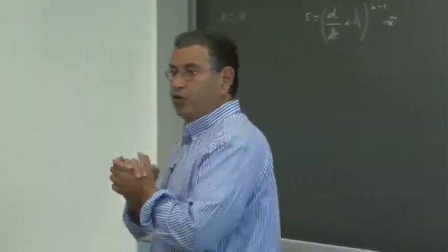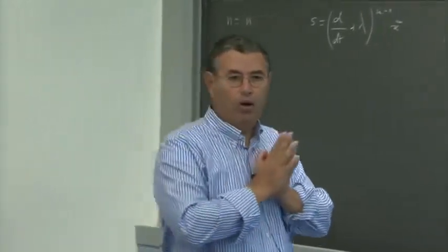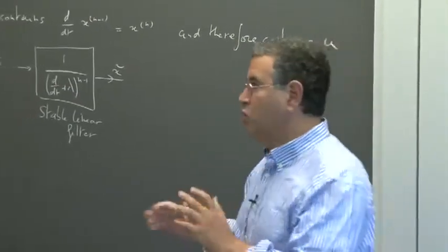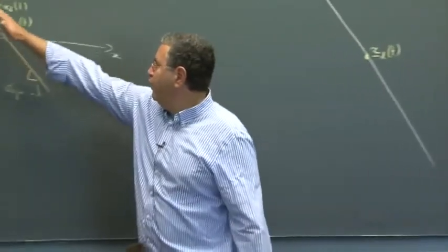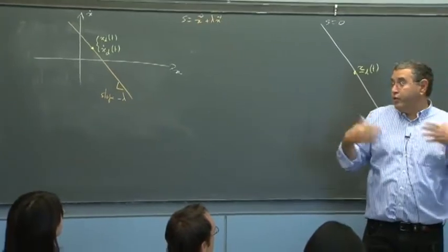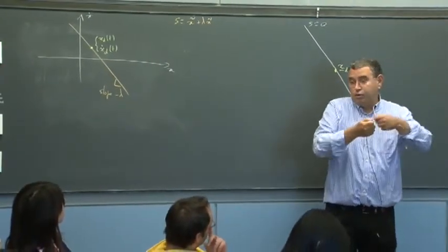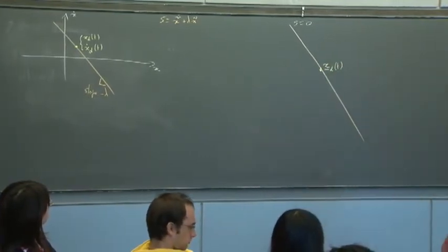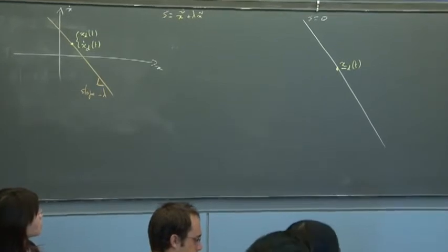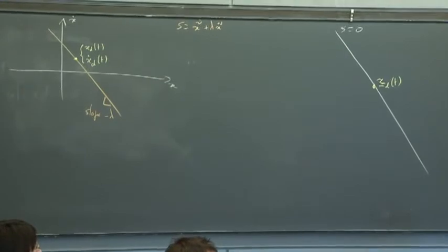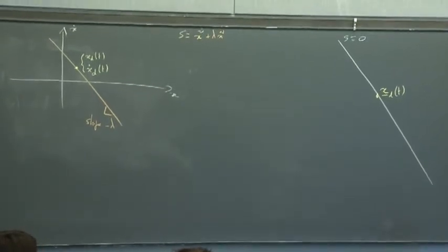Now, suppose that somehow you've made S tend to 0 and stay there. In other words, you've constructed a control law such that this is an invariant set for a non-autonomous system, namely once you start there, you stay there, and that you tend towards this invariant set. So suppose that you've managed to make the system tend to 0 and stay there. Let's even say, for conceptual simplicity, you manage to get it to tend to 0 in some finite time and stay there.